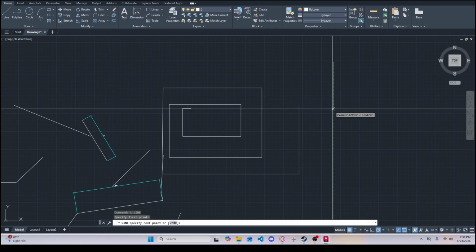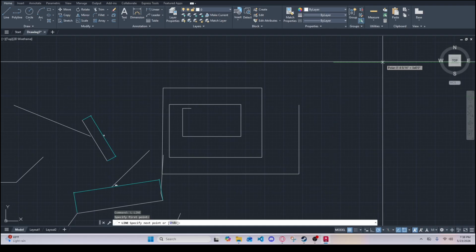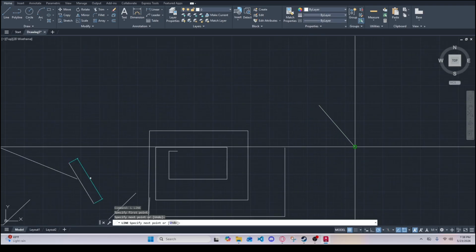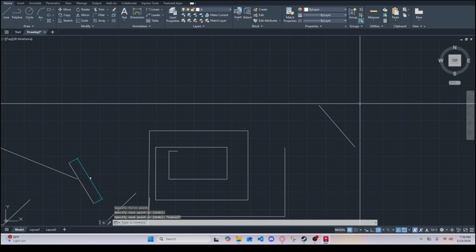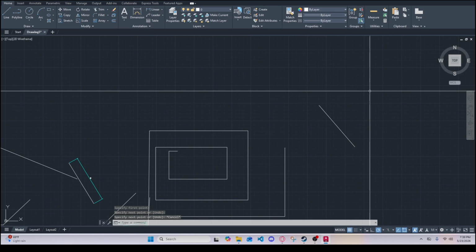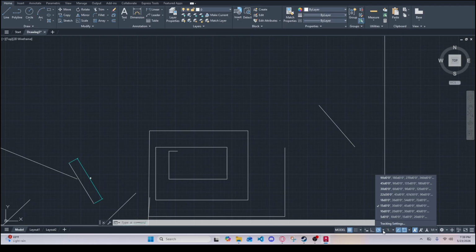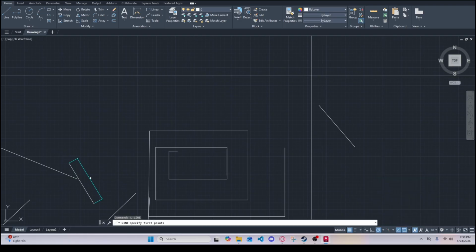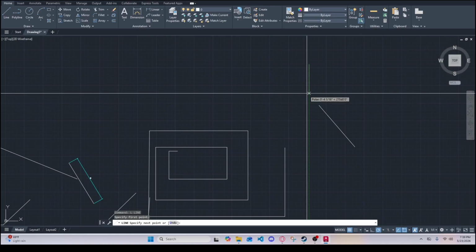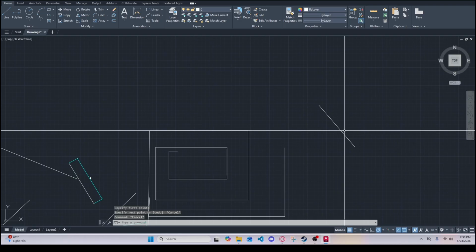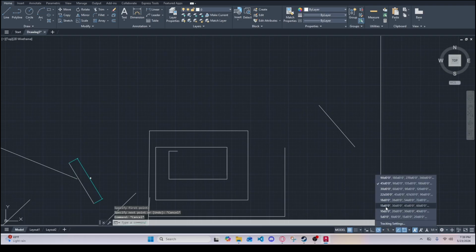So right down here is 270, obviously all the way to the right is your 0 degrees, all the way up your 90 degrees, and it's going to go up by increments of 15. It's very helpful for a lot of things. I personally like to use F10 mainly rather than F8. If 15 is too big for you, you can always do it at 45 degree angles, and it will only show up at your 45s. So it all depends on preference, but 15 degrees is typically good for me, and just in general standards.